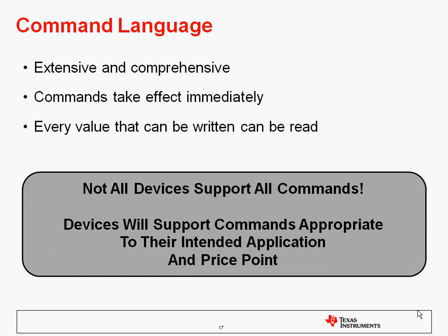So let's move on to the protocol. The command language is very extensive. There are over 100 commands in PMBus. It's very comprehensive. Any command takes effect immediately, and anything you write, you can read back. It's important to note that not all devices support all commands.